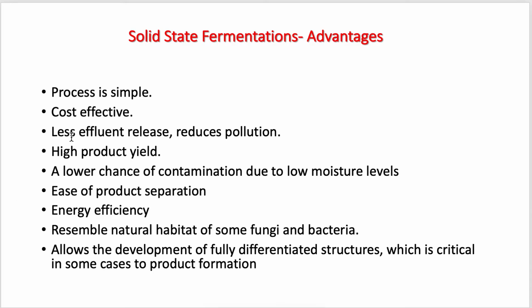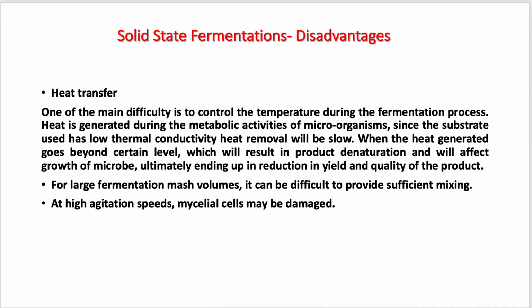So these are the advantages of solid state fermentation, but it also has some disadvantages. Heat transfer is a problem. Whenever fermentation occurs, the microbes do metabolism, and metabolism produces heat. In solid state fermentation, controlling the heat is sometimes very difficult, because there is no cooling system like that used in liquid fermenters.